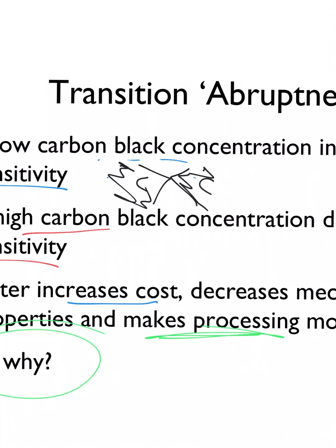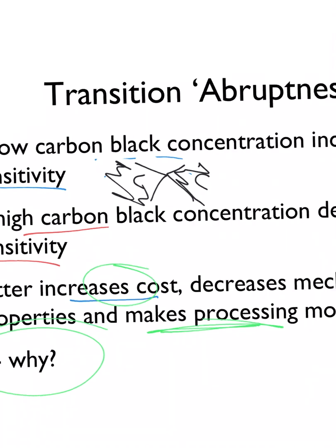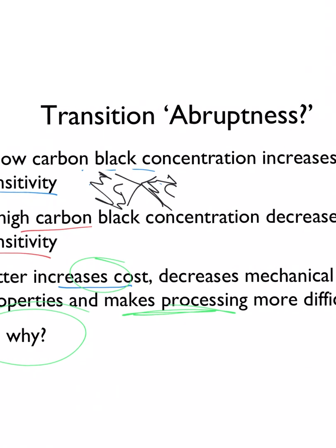And all that is flowing through steel. All right? And if we have a lot of carbon that's flowing through this melt, which is flowing through steel, it's wearing on that steel. Right? These are inorganics, and so they'll start wearing on the steel mold. You also have to use high pressures to get this stuff to flow through, even if it's at 200 degrees. It's still pretty viscous. I mean, polymers, they're not water at 200 degrees. They're still pretty viscous, and you add a solid to it, that viscosity shoots way up. All right, so these can be bad things, and that's really why the cost goes up, because of the associated processing difficulties that come with that increased carbon content.